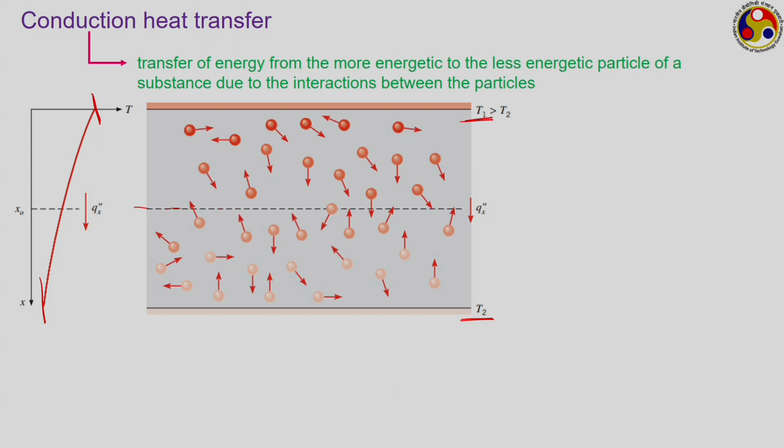So, there the collision or vibrational energy based transfer is more dominant, there is hardly any molecular movement in case of solids, whereas in case of gases the molecular movement is the most dominant one. And also for solids we can have two kinds of solids. If we are talking about non-conductors, then the one that I mentioned, that is predominant, that is the vibrational energy being transmitted to neighboring molecules.